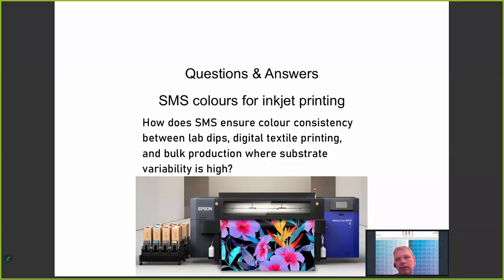So for instance, if you offer printing to FOGRA 39 standards, you should stock up on coated neutral white paper or neutral white substrate, textile or whatever, with a white point as close to the Lab value of 95, 0, -2 as possible.